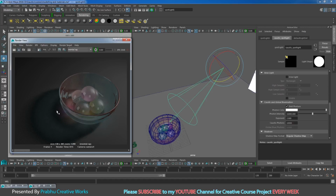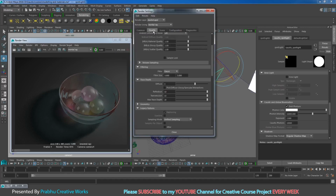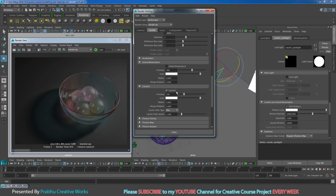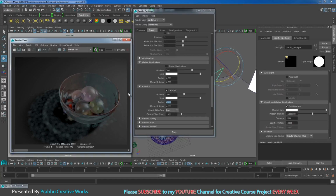Now I want to work on our caustic patterns. So go to render settings, in the quality tab. Here we have caustics turned on. At the bottom side you have radius. I will give 0.5 and press enter. I will keep this image for comparison and click render again.